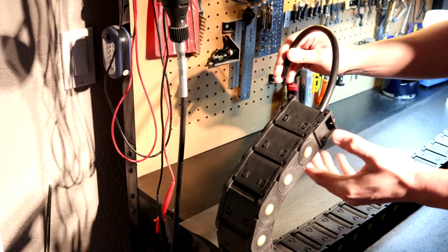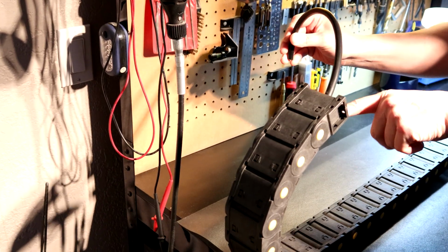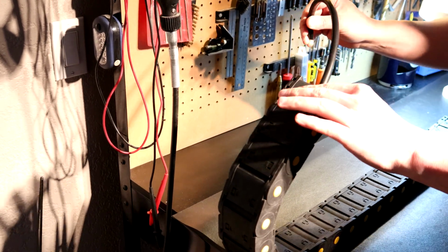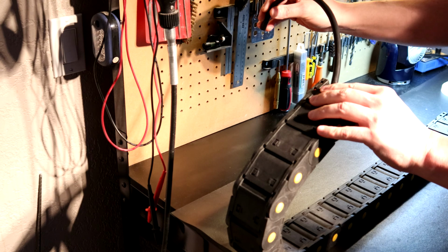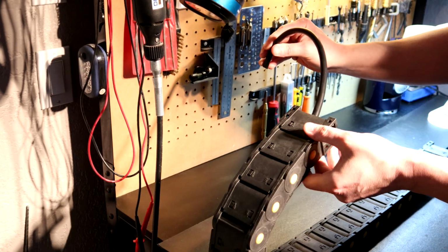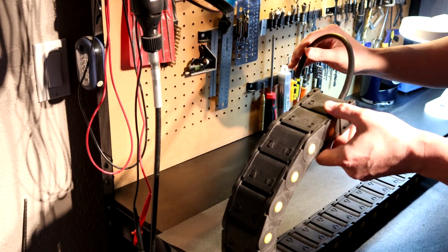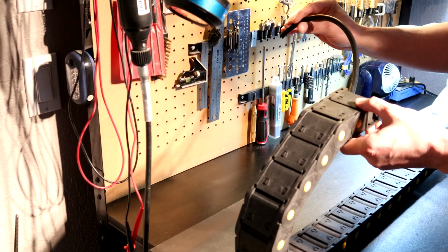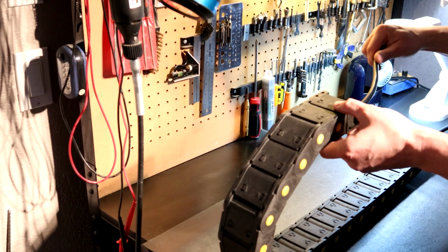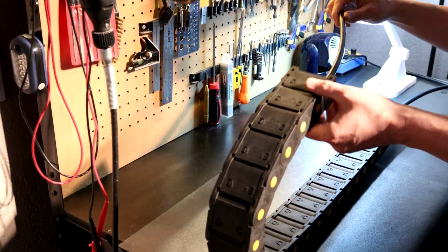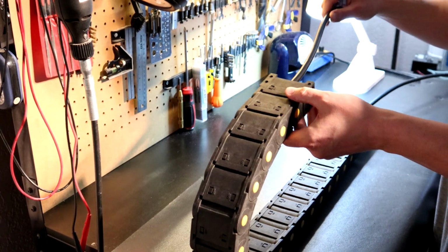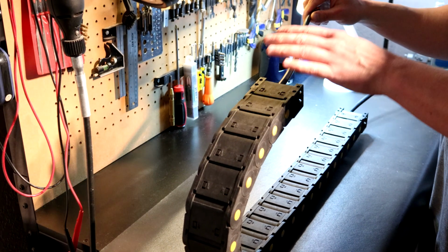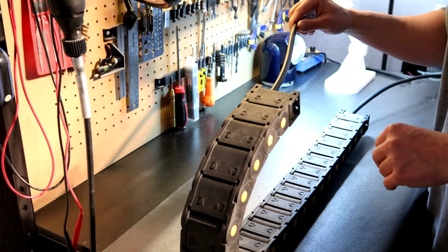Okay, so once again, we're dealing either with friction on these chains being overloaded with too many cables in them and not having the proper clearance, like discussed in the video overview on how to select a cable chain, or they're cutting corners on the cable length, which I've seen done time and time again. As we go on, you'll find the shorter the cable you use, no different than covered in the video, usually the shorter the lifespan of the cable.